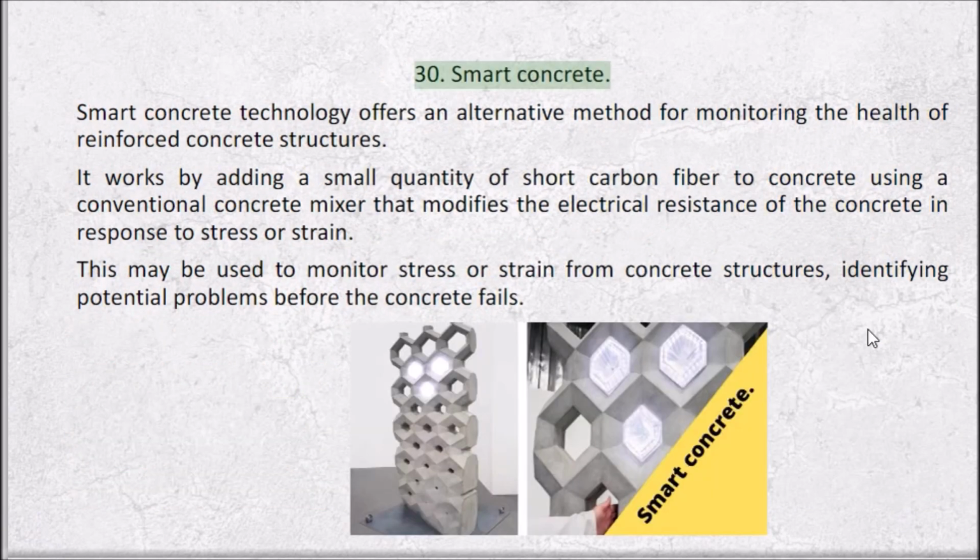30. Smart concrete. Smart concrete technology offers an alternative method for monitoring the health of reinforced concrete structures. It works by adding a small quantity of short carbon fiber to concrete using a conventional concrete mixer, which modifies the electrical resistance of the concrete in response to stress or strain.